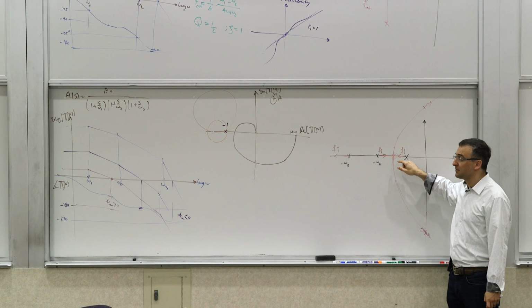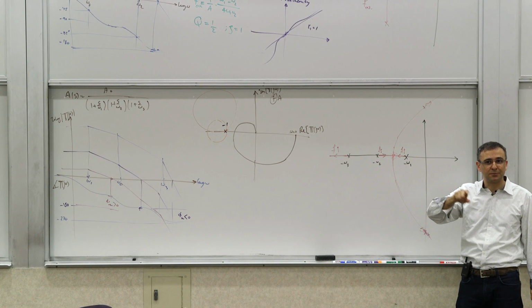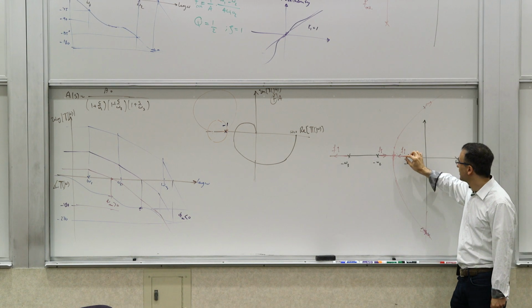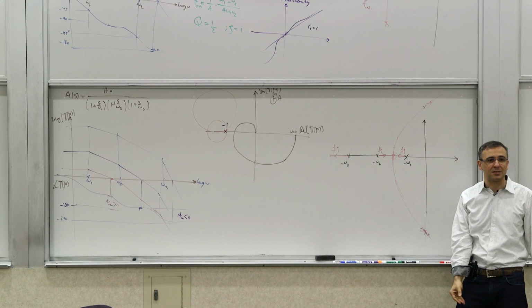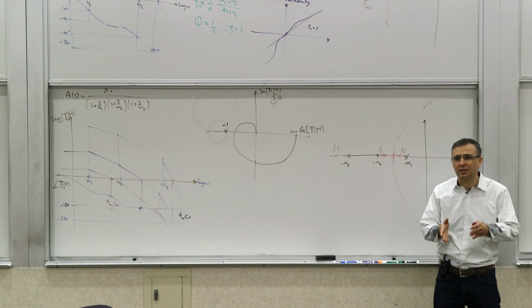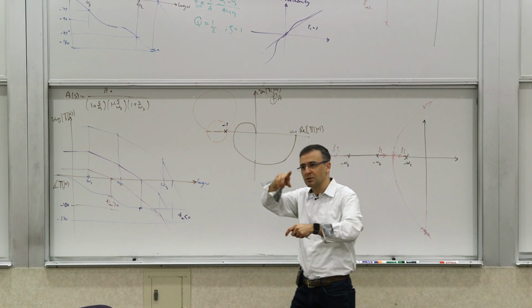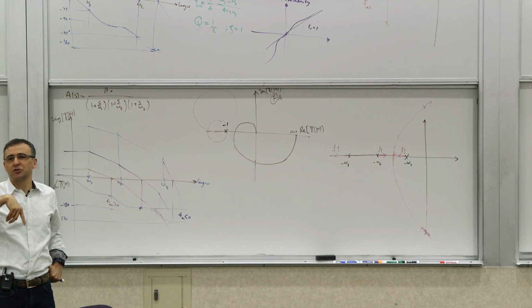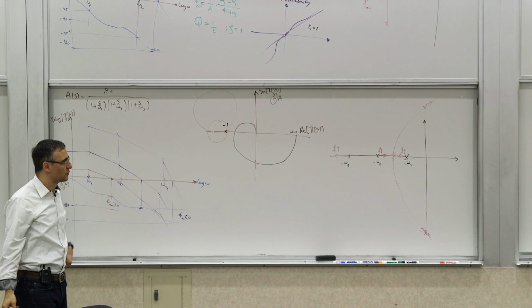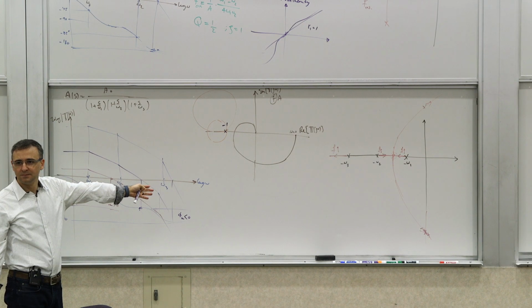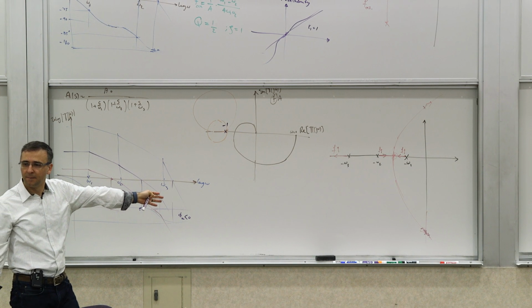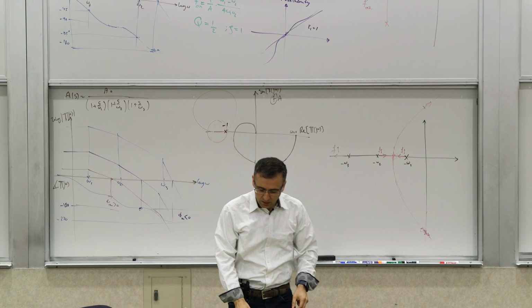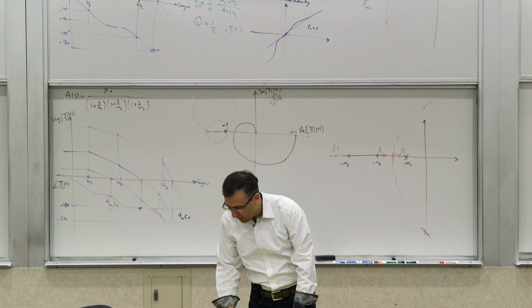Then as we increased feedback, they became complex, because we saw ringing in the transfer function. And as we increased it further, at some point it became unstable, and for a bounded input we had an unbounded output. The step responses started growing as an exponentially growing sinusoid. So that's what we get from an amplifier.